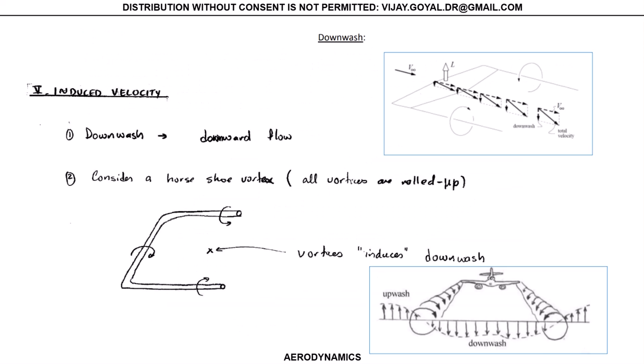Okay. So the vortices here at the tip are the ones that are responsible for the induced velocity. Induced velocity is nothing else than what we call a downwash velocity, and we just talked about this in the previous couple of classes, where we said there's an extra amount of drag that's actually created.